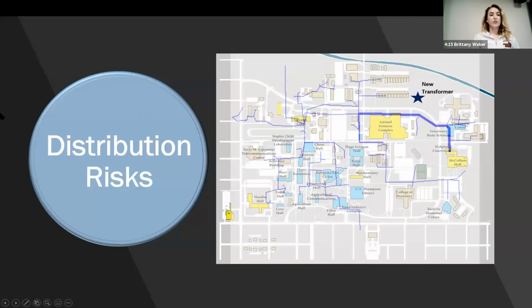A risk for our distribution system we found was that the per unit voltage dropped out of range significantly below the 0.95 voltage minimum as the distance increased. We implemented a smart inverter control and tried to control the PV systems individually by defining the per unit voltage minimum of 0.95 and a maximum of 1.05 in each PV system definition. However, this still did not resolve our issue.